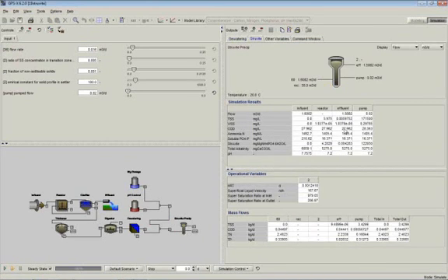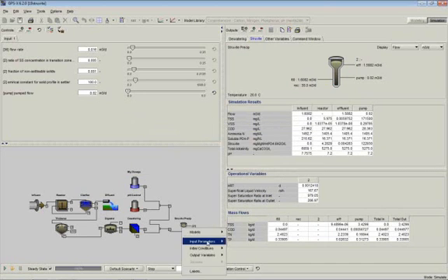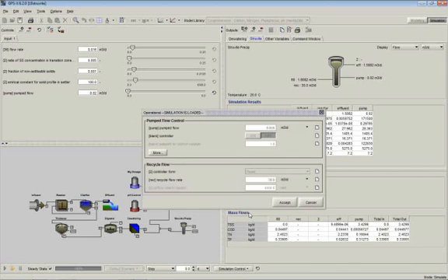So if I look at the details here, we can see that it's doing both the precipitation chemical reactions in this object as well as the solid separation through that bed, all in one step and all in one model. You have the ability to define its physical characteristics, such as its height and cross-sectional area. Places where you may have a recycle happening, you can do that as well.